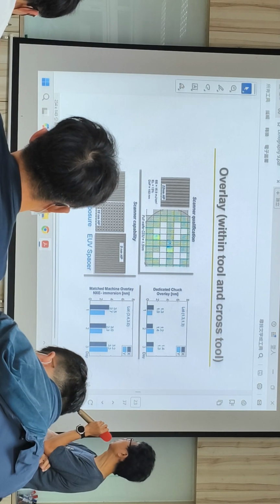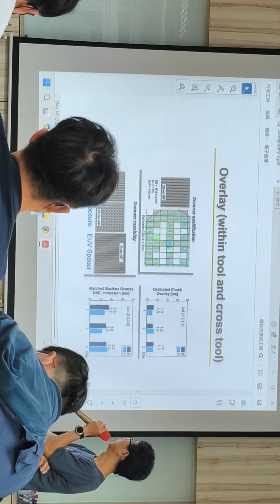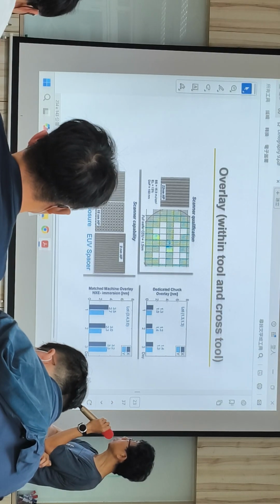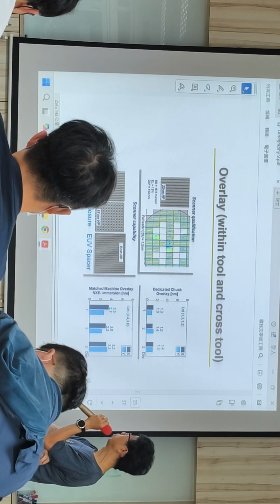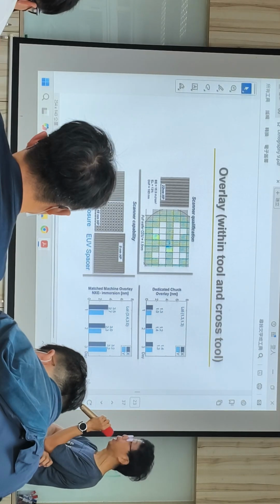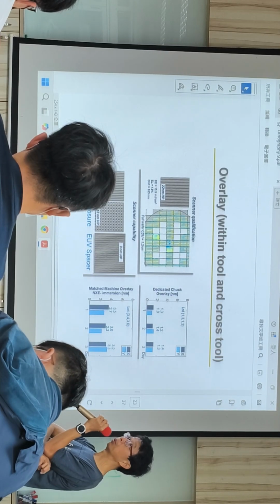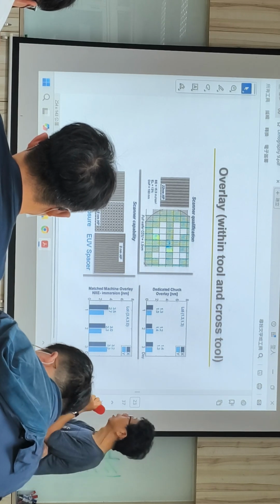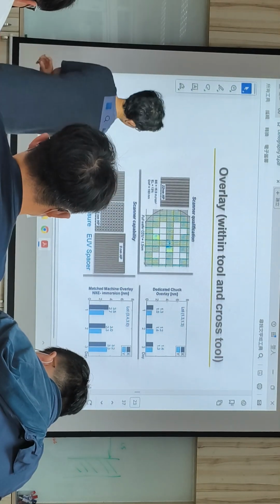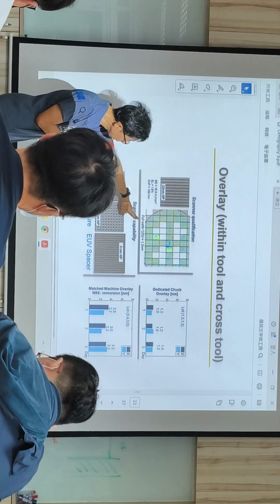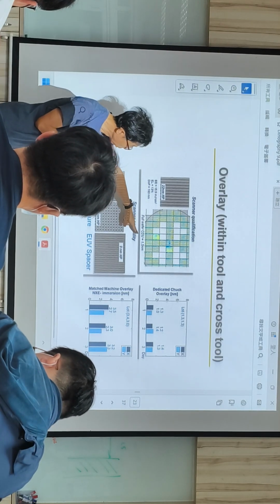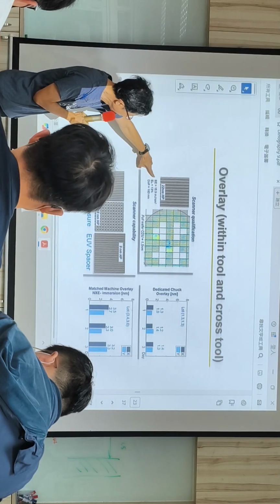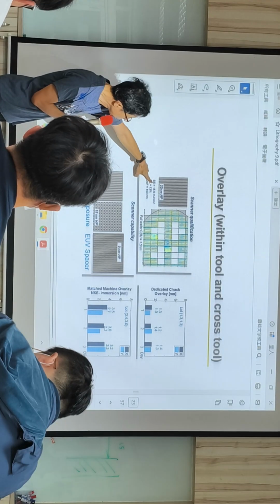Okay? So as you can see, single machine overlay can reach about 1.3, and matched machine overlay is 3.4 nanometer. So in a sense, it's pretty decent. Okay, and you can see here the full wafer CD uniformity is 1.5. This is for scanner qualification.